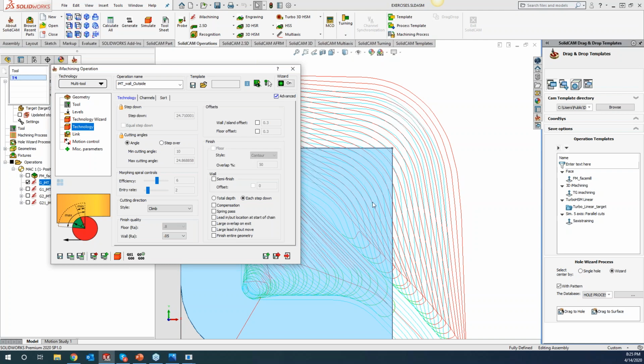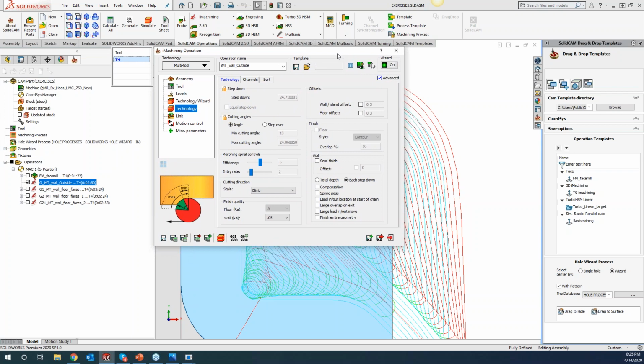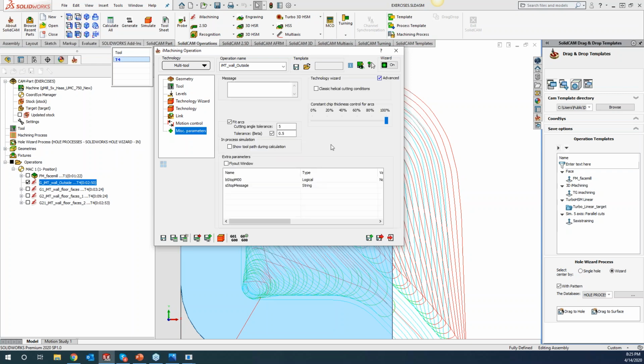Any harder materials, like Greg is saying, you know, you get into the softer materials, you shouldn't see any difference at all. But like exactly what you're saying here, Greg, we like to push our tools to the absolute limit. So if you're trying to push your tool to the absolute limit and you're in a time crunch, don't keep that miscellaneous parameter for the tolerance down at the default, just so you're not over engaging that tool.